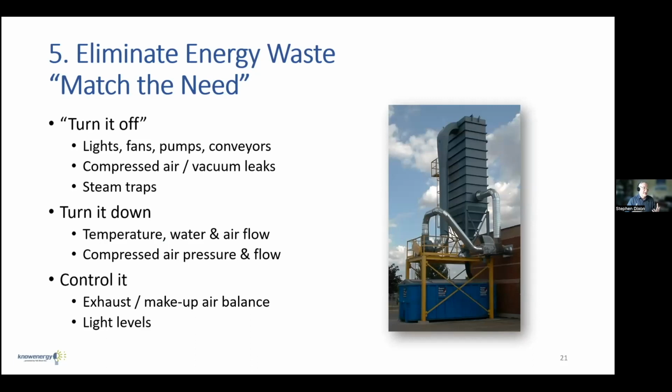Making sure that things aren't running. To be honest with you, in every energy assessment that I've been involved with in the past, and even lots of existing building commissioning studies that are done today, what we find is simply scheduling things properly is still probably one of the number one opportunities, not just things like leaks, compressed air, steam in industry, but just the way lights and fans and pumps are actually operating, making sure that we only operate them when we need to. If we can't turn them off, can we turn them down? And that's where things like drives come in.